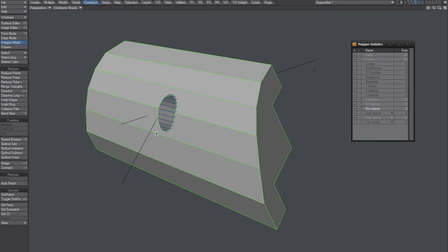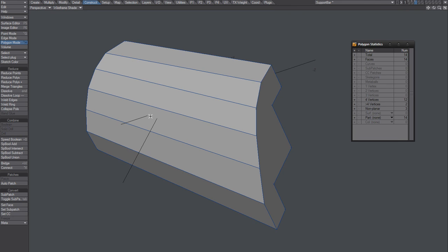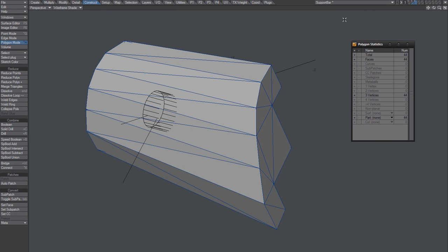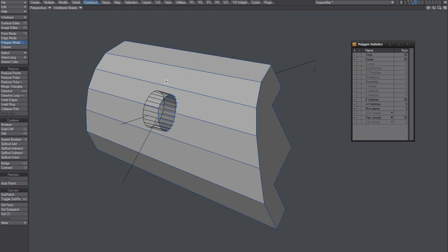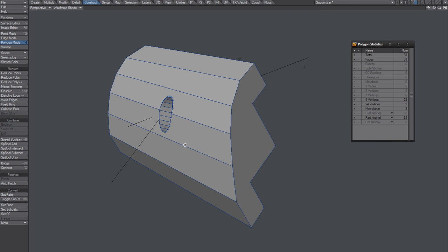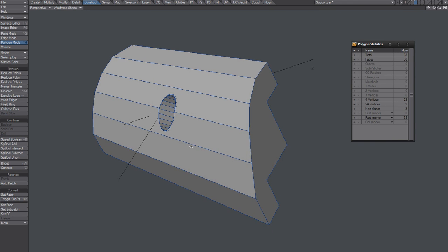Sometimes the Boolean operation can be difficult, and what you need to do then is to take this object and triple it, and then use the Boolean. You might even want to triple that disk shape. Boolean, subtract, okay. But for now it worked okay. So that's it. Just some info for a newbie.